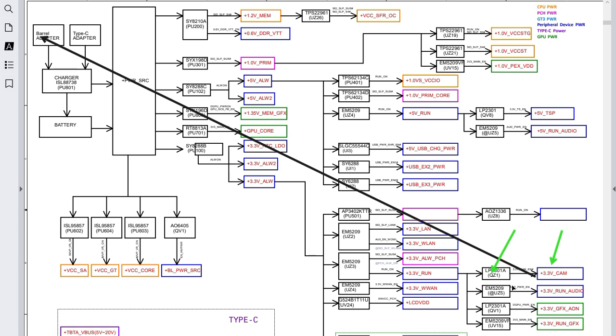So we should go back and look for the source, the IC that feeds this IC. This is the IC responsible here. This IC is the one that controls this IC. So we should check this one. We didn't get plus 3.3 volt here for this IC. Does it mean this IC is bad? No, we should check the input. The input here should be 3.3 volt. So we should check whether we have 3.3 volt or not.